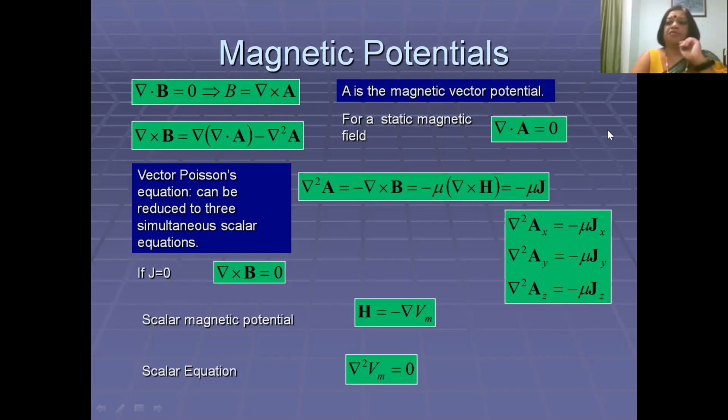So right now you're in a position already. Remember, I told you that the reason I spent so much time on the electrostatic fields problem and developing the finite elements method based on it is that once you have done that, you have actually done a lot more than you expect. Now, if you want to solve the magnetostatic field, all you need to do is solve these equations 3 times and you will get the 3 different components, put them together and plot the field B. Is this point clear to everybody?